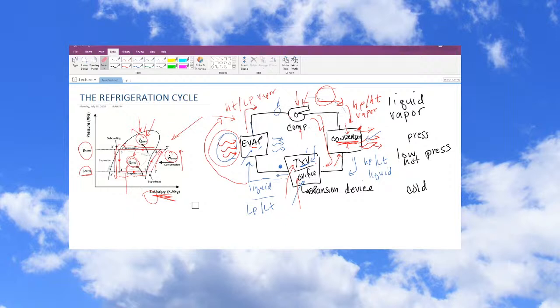So the first thing when you have a problem and you get a check engine light, it says camshaft too advanced. Well, what does that mean? And you look at what the book says, and it says that after so many cycles, it shows that the camshaft position is outside of this delta from target, whether it be 10 degrees or whatever, right? And then you go, okay, well, is that true? That's the first step. Is it true? Is that signal even correct? Is the ECU responding to an inappropriate signal, or is it responding to an actual inappropriate condition? And so you have to think about, okay, one, what creates that signal? And is the signal right?